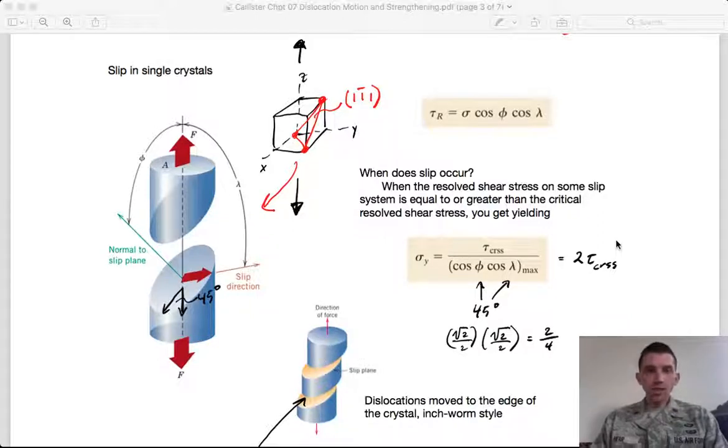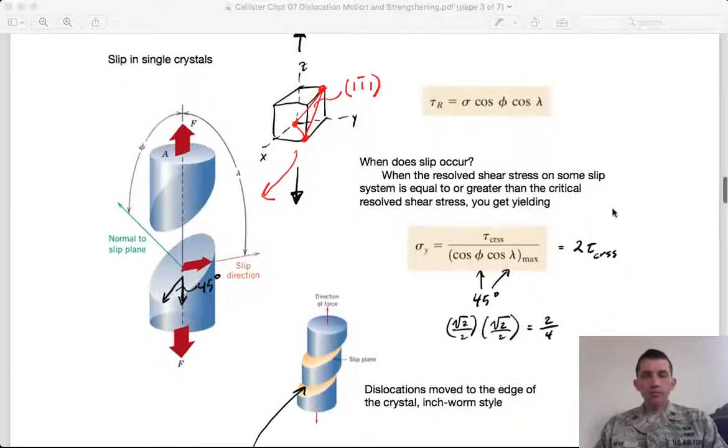And so, what are the conditions under which slip occurs? Well, first you need to have a slip plane, and if you don't have one, eventually, if you increase the force enough, you'll find one. But the minimum condition is going to occur where you produce what's called a critical resolved shear stress, right?